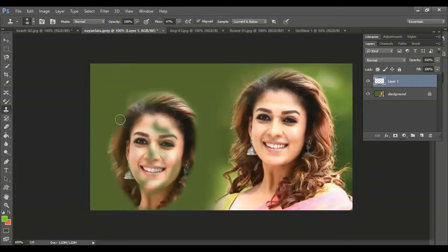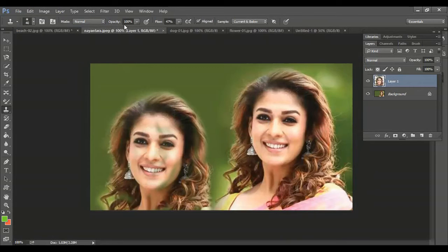So you are applying paint once again, and it becomes like that. So you can adjust the intensity by using the flow. That is not possible using opacity. Opacity, its transparency is fixed. Even if you move your brush many times, you cannot bring back that transparency. It depends upon the opacity there. But in the flow, you can bring back.